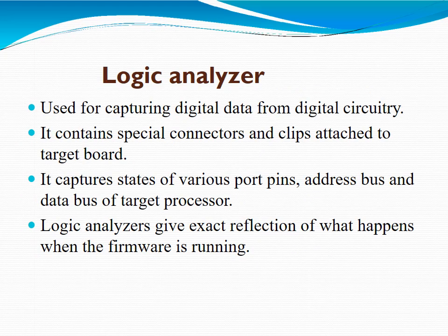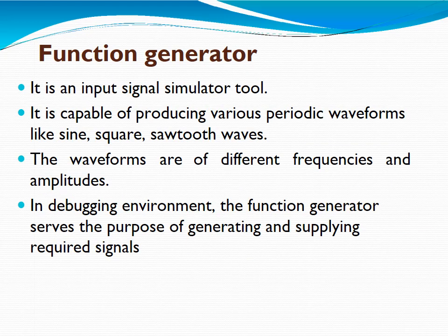The next one is logic analyzers. Logic analyzers capture digital data from digital circuitry. They have special connectors and clips for the target board. They capture the address bus, data bus, and target processor signals, giving an exact reflection of what happens when the firmware is running. So the logic analyzer is another form of target hardware debugging to analyze various digital circuitry of the embedded system design. We can predict the address bus, data bus, and various port pin functions by means of these logic analyzers.